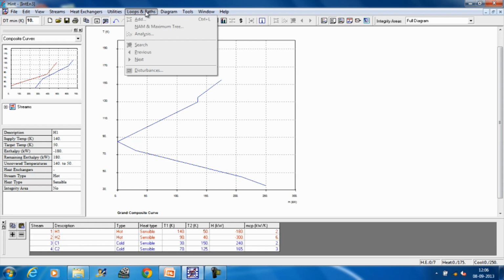When we go for the design of a heat exchanger network, the first design is a MER design, maximum energy recovery design, and then the maximum energy recovery design is further modified to get a low cost heat exchanger design by avoiding, or you can say violating, the pinch in that, to save the number of units.